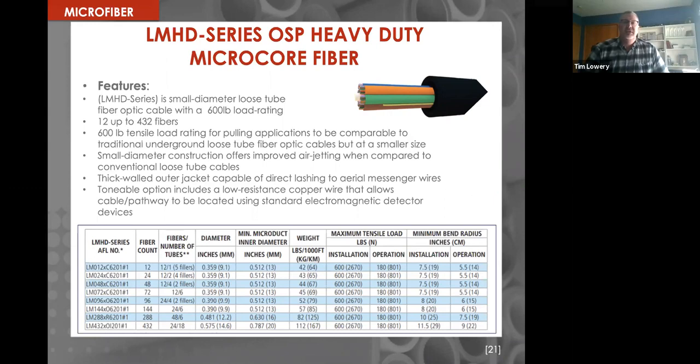The advantage that we see is in the future path ducts, it reduces the amount of condensation or water that could penetrate the cable. David can touch on that. So it actually has a little bit better advantage that we're not seeing the expansion and contraction due to freezing as much, because that pathway stays more dry than a traditional 1.25 or 2 inch inner duct. As far as any other water, we've had the cables installed, like I said, for 10 years here in the Northern Illinois area with no negative feedback from heat and or cold.